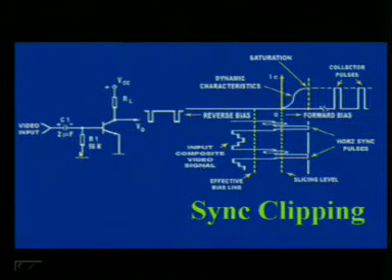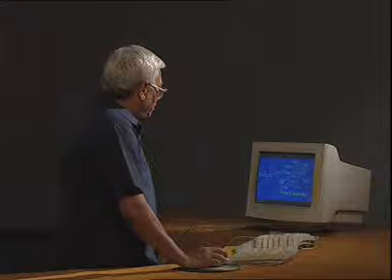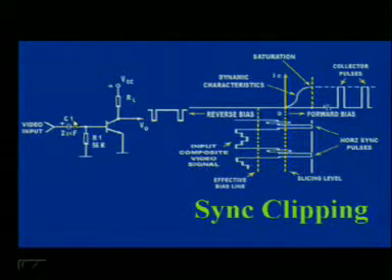Now, through this circuit, let us see how the sync is separated or clipped. Basically, this is a sync separator stage, which has one active device, a transistor, and two components, C1 and R1. They are for the biasing purpose of the base of this transistor. Here in this figure, C1 is of the value of 2 microfarad and R1 is of 56 kilo ohm.